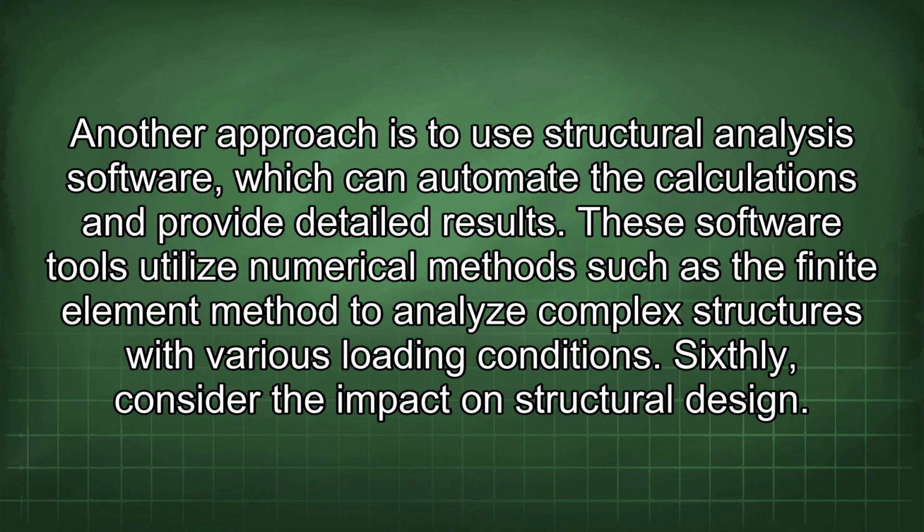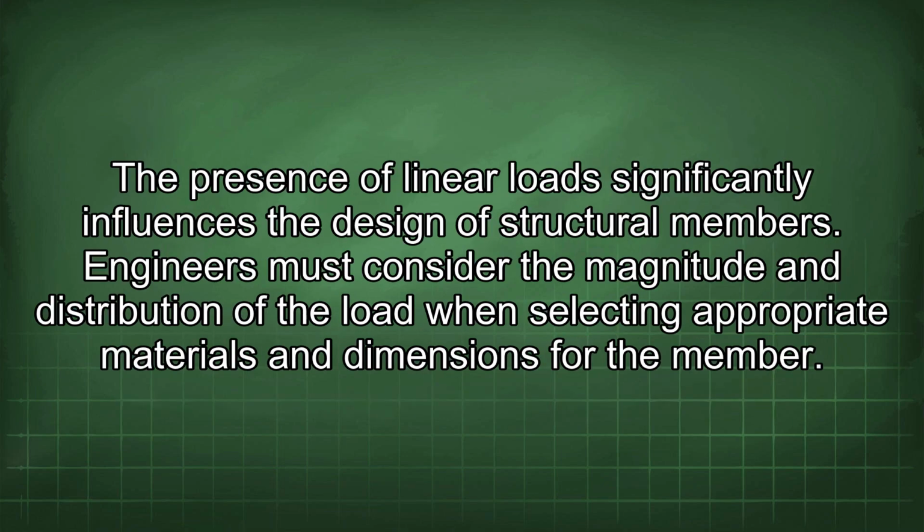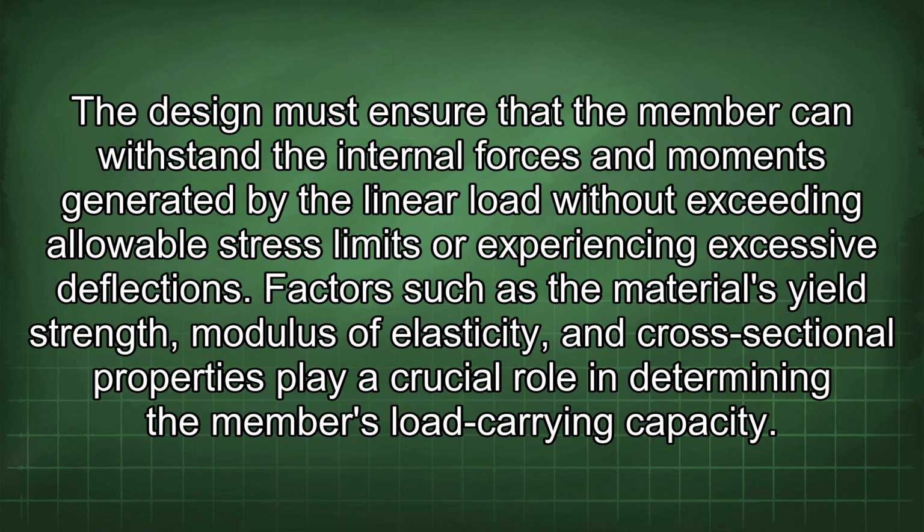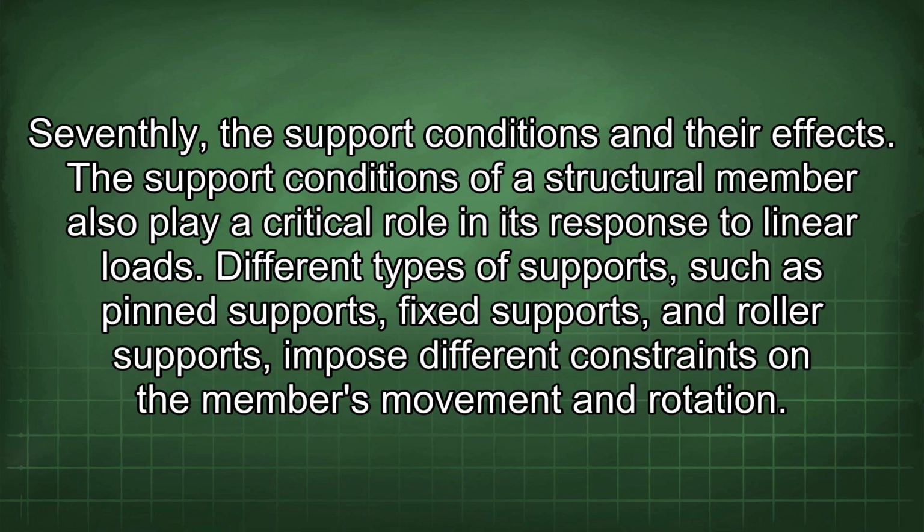Sixthly, consider the impact on structural design. The presence of linear loads significantly influences the design of structural members. Engineers must consider the magnitude and distribution of the load when selecting appropriate materials and dimensions for the member. The design must ensure that the member can withstand the internal forces and moments generated by the linear load without exceeding allowable stress limits or experiencing excessive deflections. Factors such as the material's yield strength, modulus of elasticity, and cross-sectional properties play a crucial role in determining the member's load carrying capacity.